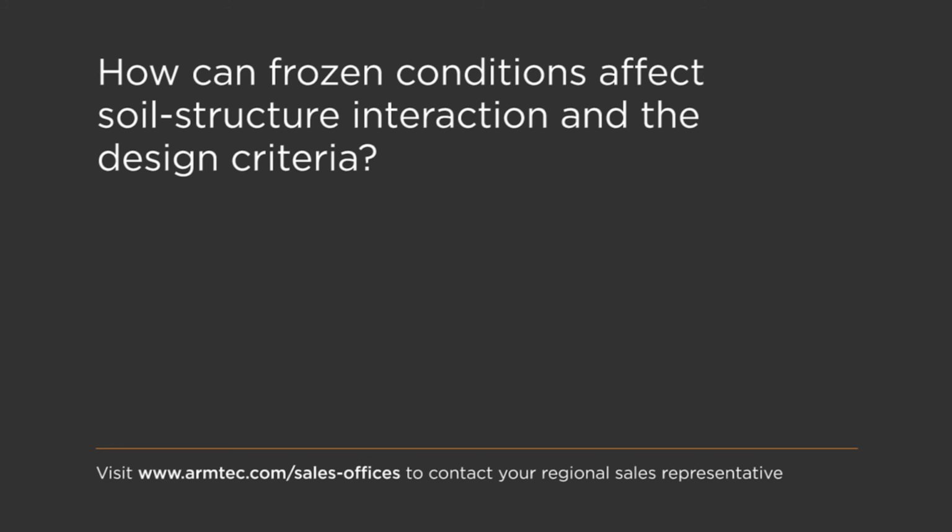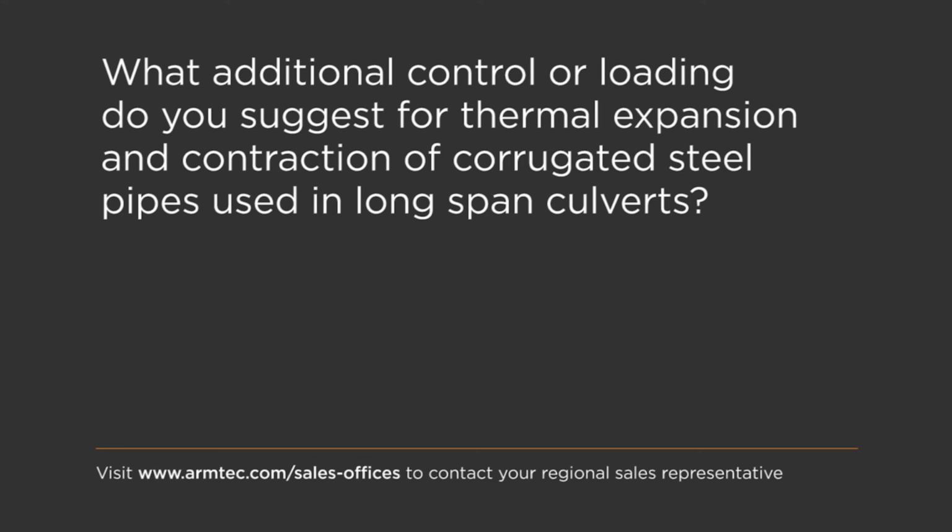So how can frozen conditions affect soil structure interaction and design criteria? And I'm going to tack on the next one because it's specifically related to the same question. What additional control or loading do you suggest for thermal expansion and contraction of corrugated steel pipes used in long span culverts? So this is all the same question coming from the north here. Yeah, so in terms of thermal expansion and contraction, soil steel structures are very well suited for minor settlement. They are flexible structures, so they are meant to move a little bit. So those types of forces are normally not a concern, depending on the severity of that. But generally speaking, that's not something we worry about.